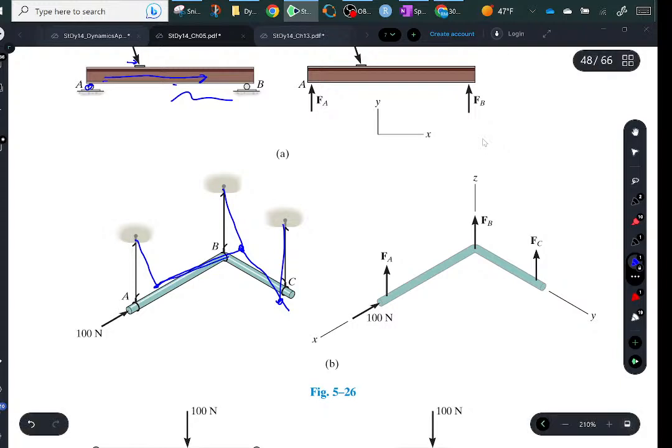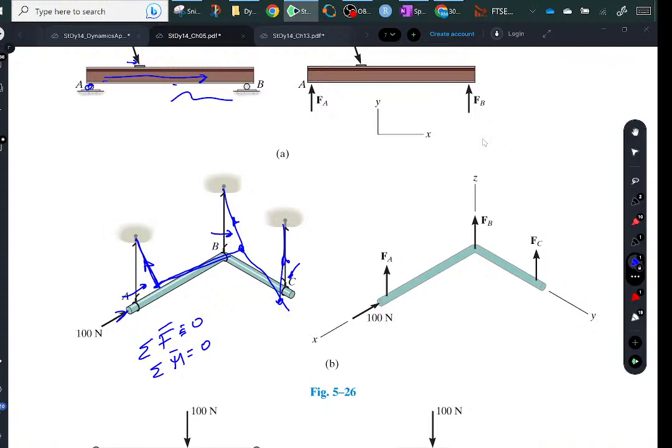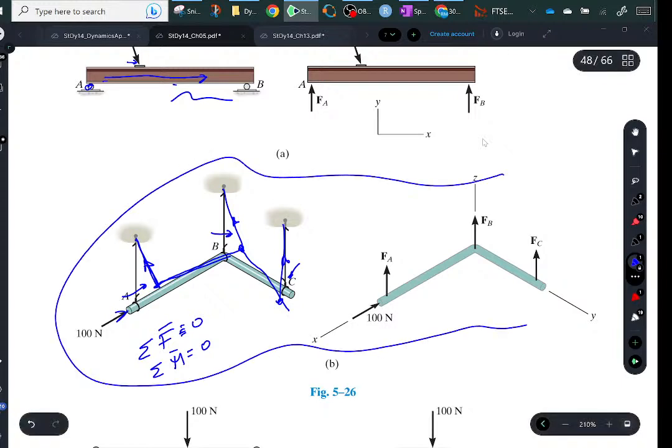So if that makes sense, you push it this way, the rope is going to stay the same length, but it's going to move that way. Probably this one's going to move a little bit that way, and this one's probably going to move a little bit that way, so that the tensions offset this force, and you'll end up with sum of all the forces equals 0, and sum of all the moments will equal 0 as well. So it will force itself into that. So this one's a little bit different. You can do this, but don't expect it to stay vertical.